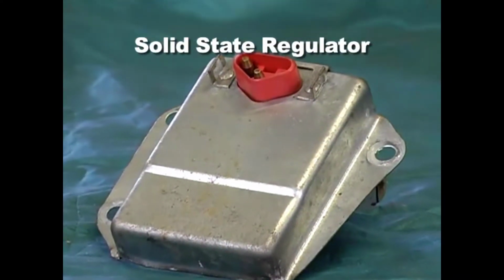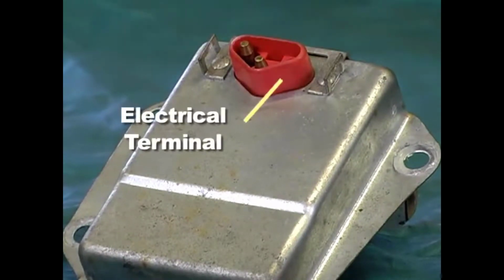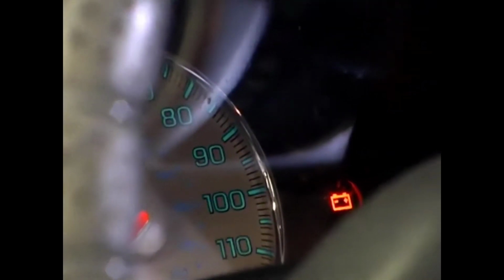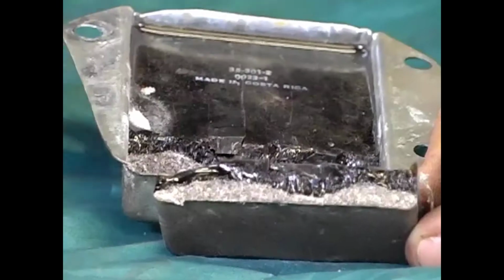The next improvement was the remote solid-state voltage regulator. Note the electrical terminal for connecting to the stator, field, battery, and indicator light. This allowed the remote regulator to sense output and adjust it up or down as needed. It allowed the regulator to turn on a warning light if voltage dropped too low.